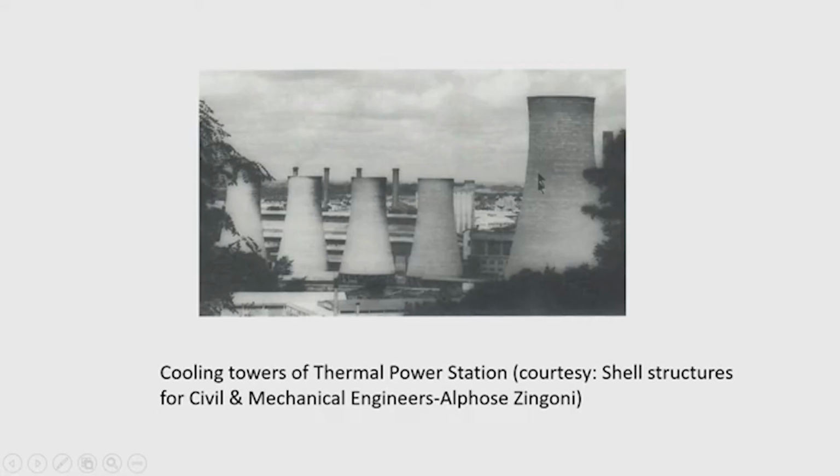It is constructed of reinforced concrete and steel, and has to resist the self weight and other imposed loads. Therefore, the design of this type of cooling tower is very important for the safety of the industrial operation, and the design is generally done using the membrane theory of shell.